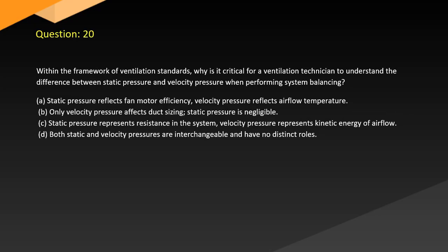Question 20. Within the framework of ventilation standards, why is it critical for a ventilation technician to understand the difference between static pressure and velocity pressure when performing system balancing? A. Static pressure reflects fan motor efficiency, velocity pressure reflects airflow temperature. B. Only velocity pressure affects duct sizing. Static pressure is negligible. C. Static pressure represents resistance in the system, velocity pressure represents kinetic energy of airflow. D. Both static and velocity pressures are interchangeable and have no distinct roles.